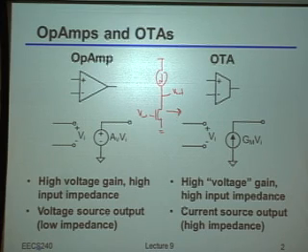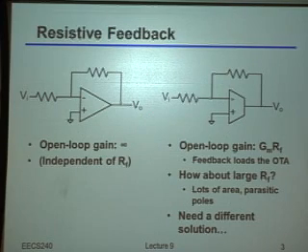Okay, so why is this an important point to realize? Well, having really high DC gain is, of course, great, but typically is not that easy to use just by taking that op amp and throwing inputs into it. Right? Typically, you put things into feedback to actually know what the gain you're applying is, and also to make sure you don't just rail out all of your signals.